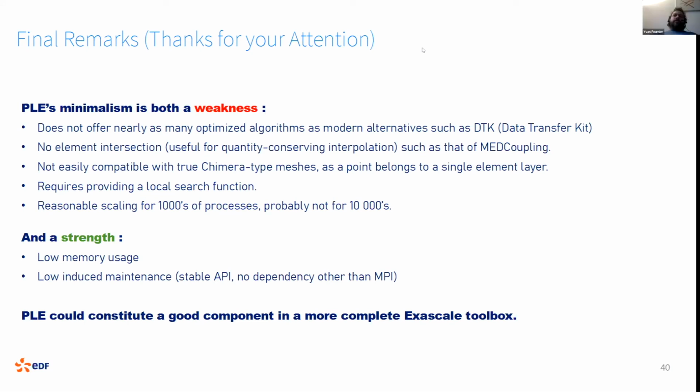So in this case, basically, it'll depend on the partitioning. We have PLE exchange the point coordinates, but the elements stay on the matching mesh. So there will be some sensitivity to domain decomposition. And for example, we don't have any rebalancing aspects. So for example, when we're doing surface coupling, parts which don't have any surface cells won't participate, and only the parts that do have surface cells will work. So there's no explicit balancing. The balancing is strongly dependent on the partitioning.